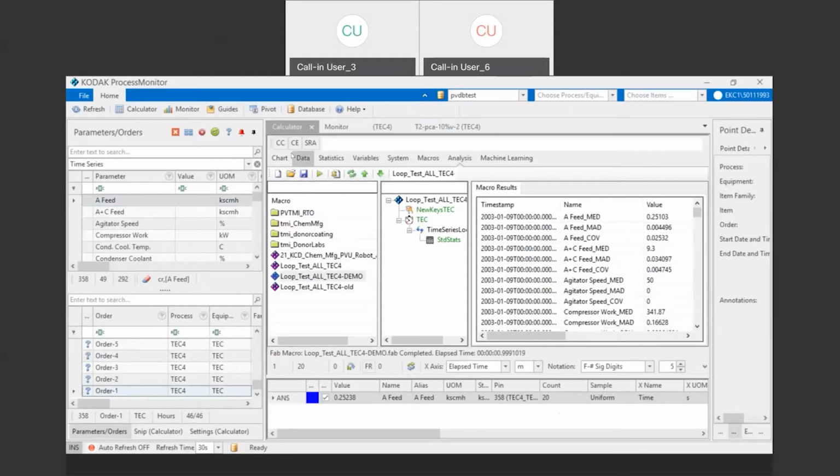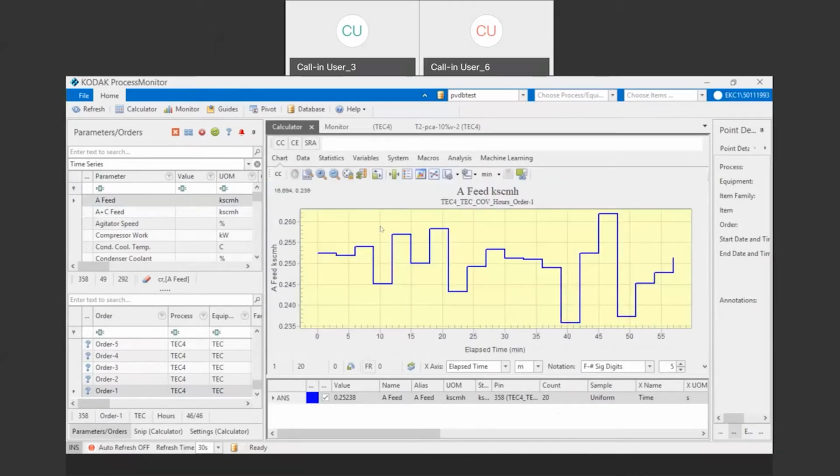So basically, when you look at it, we would show a time series, and the scan rate is once every 3 minutes. It's interesting, Dan and I were talking about this. Depending on the process and the fundamentals, chemistry, physics, and all that, this is relatively slow. We tended to do more like 1 hertz, or in some cases, hundreds of hertz. It all depends on the specifics of the process, your process understanding, and the capability of the instruments, and a lot of issues that we talk to clients about when we first engage with them.